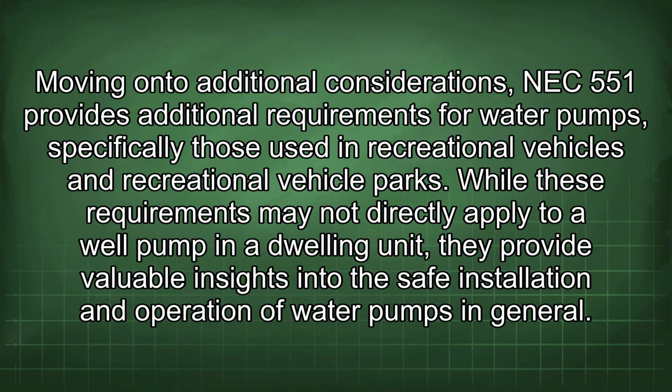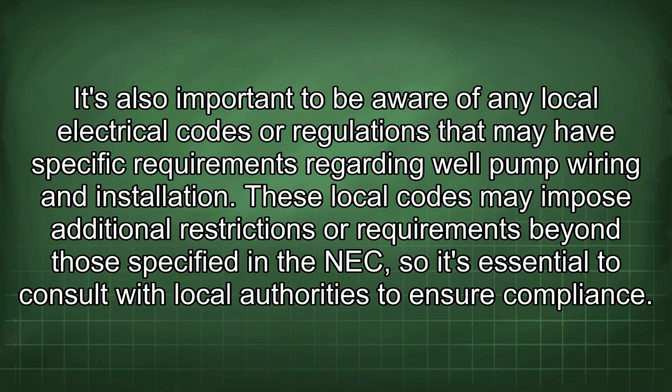Moving on to additional considerations, NEC 551 provides additional requirements for water pumps, specifically those used in recreational vehicles and recreational vehicle parks. While these requirements may not directly apply to a well pump in a dwelling unit, they provide valuable insights into the safe installation and operation of water pumps in general. It's also important to be aware of any local electrical codes or regulations that may have specific requirements regarding well pump wiring and installation. These local codes may impose additional restrictions or requirements beyond those specified in the NEC, so it's essential to consult with local authorities to ensure compliance.